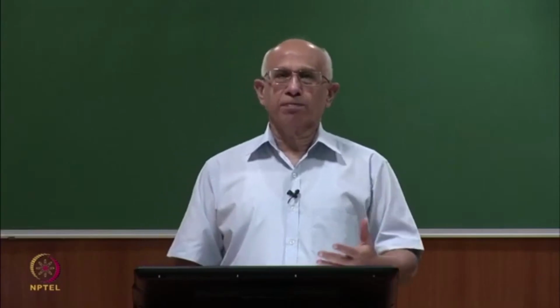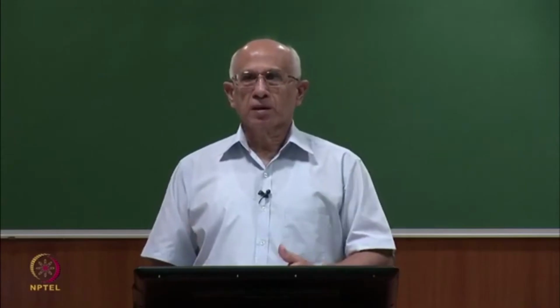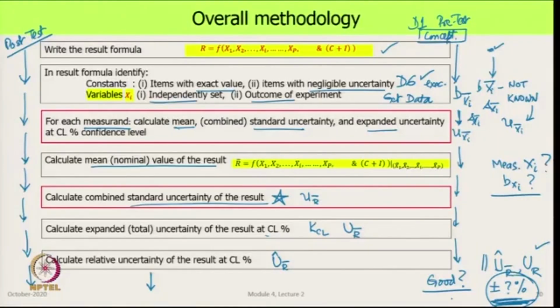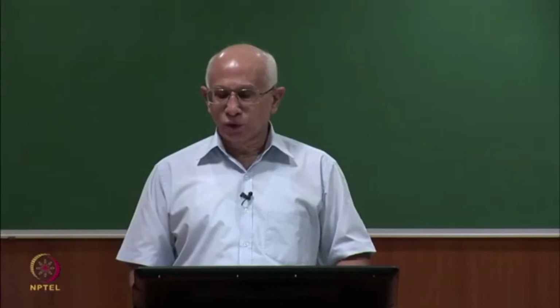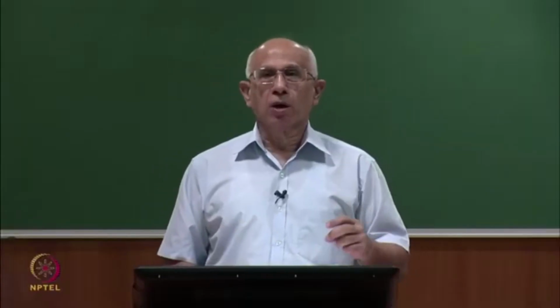And we could say, look, I have a setup, let me check what uncertainty I can get with my setup. We do that check calculation in this way and then compare it with what is needed, and we can say to them that, yes, my uncertainty is less than yours, we could do it, or that my uncertainty is more than the value that you want, my setup is not good enough for your purpose, I cannot do the experiment. So, that is an example of the use of uncertainty analysis, where even before taking any data, we can decide whether an experiment is doable or not doable.